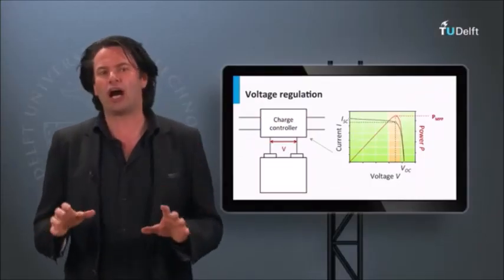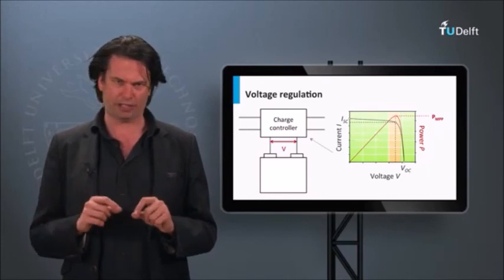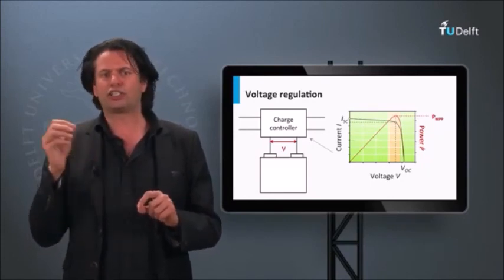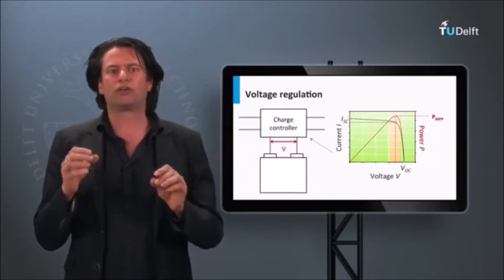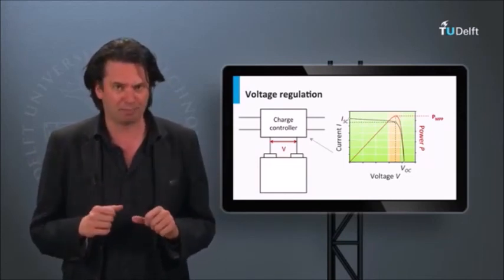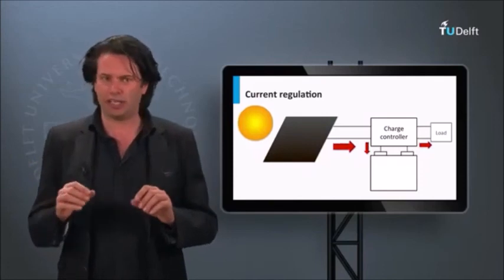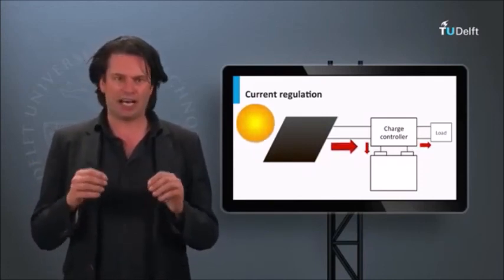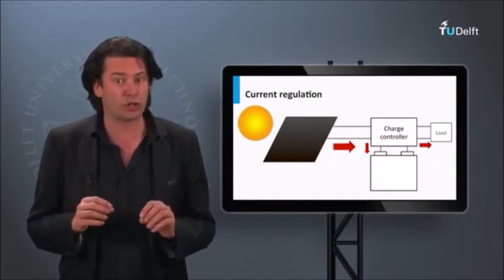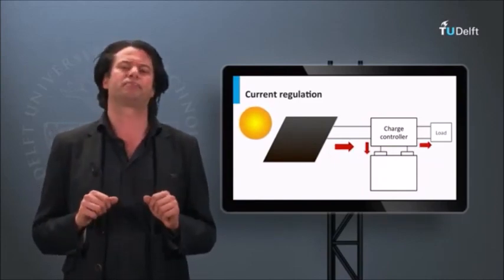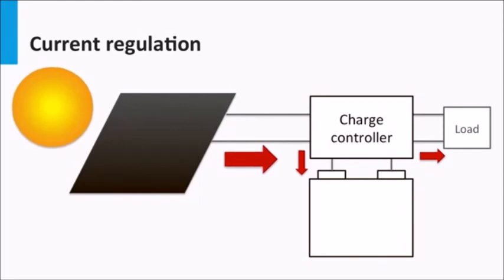We have seen before how the battery has certain C rates defined. Higher the charge-discharge rates, the lower the coulombic efficiency of the battery will be. The optimal charge rates indicated by the manufacturer could be adhered to by manipulating the current flowing into the battery. With proper current regulation, the charge controller is also able to control the C rates. At the very least, the charge controller can impose limits on the maximum allowable currents flowing into and from the battery.